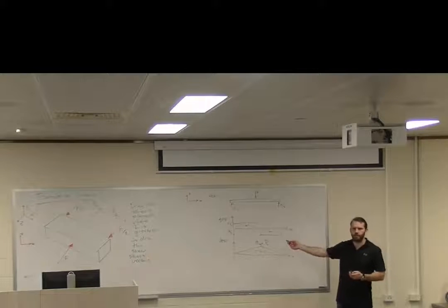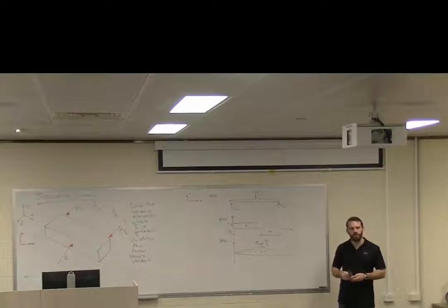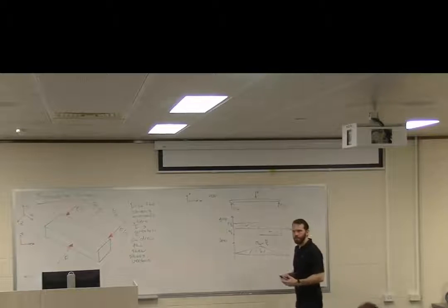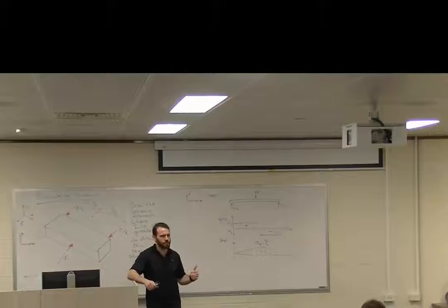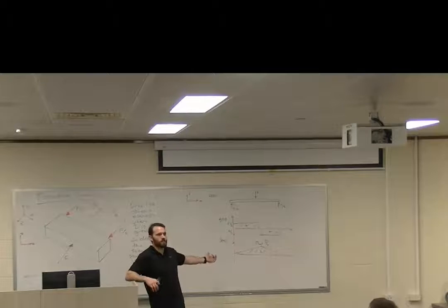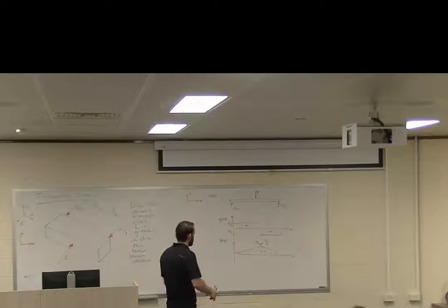Shear force diagram, bending moment diagram, free body diagram. Honestly, with this stuff, just do it as second nature. Like from a mechanistic standpoint, you just do it and you understand it and you get it right every time. Then you can use it or you can not use it. But it's sort of the first step in analysing almost anything that we do. Just do it as a second nature kind of thing. I actually didn't mean to do the bending moment diagram because we don't need it. We're talking about shear, and I just did it automatically. Because if you get that into your procedure, you just do it.